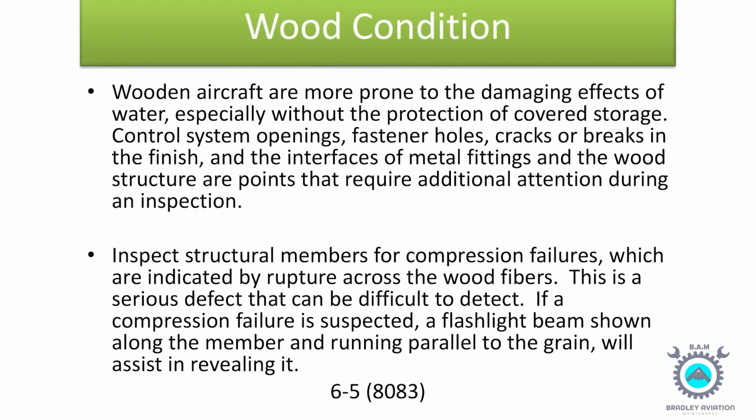Wooden aircraft are more prone to the damaging effects of water, especially without the protection of covered storage. Control system openings, fastener holes, cracks or breaks in the finish, and the interfaces of metal fittings and the wood structure are points that require additional attention during an inspection.